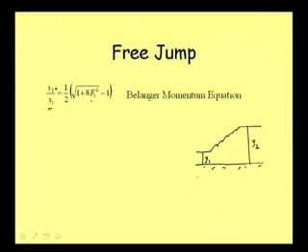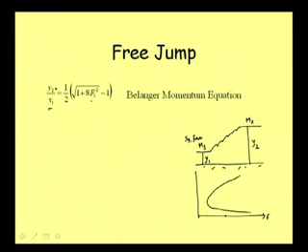If we draw the specific force diagram, because F I am already using to represent the Froude number, let me use the term M for specific force: M1 here and M2 here, and we know that M1 and M2 are always equal, M1 equal to M2.